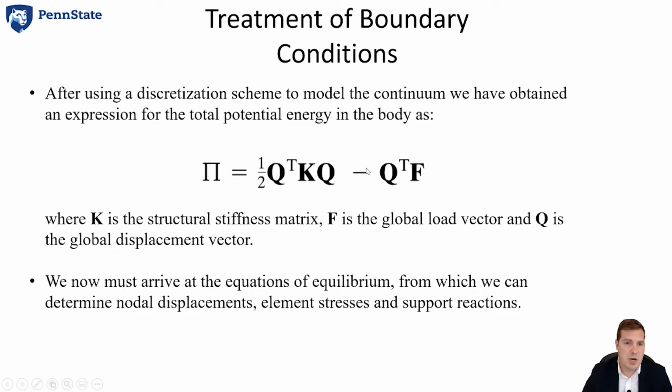So after the discretization and meshing and the assembly process, we have the total potential energy of the system represented here. We now need to arrive at equations of equilibrium where we can solve for the nodal displacements, then subsequently the strains and the stresses. So not all these Q's are known.